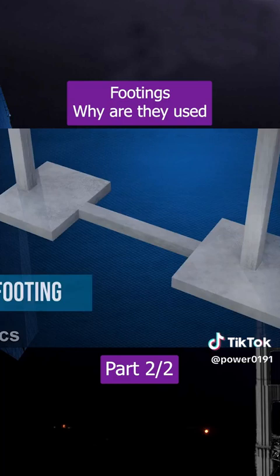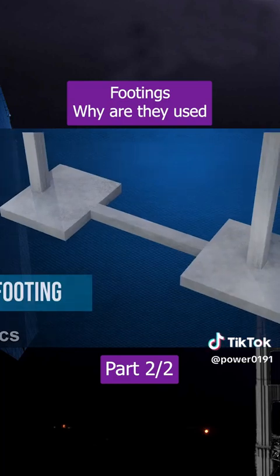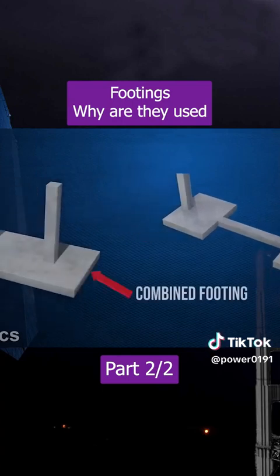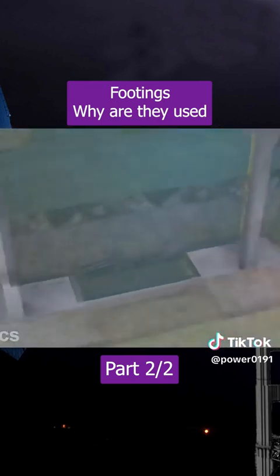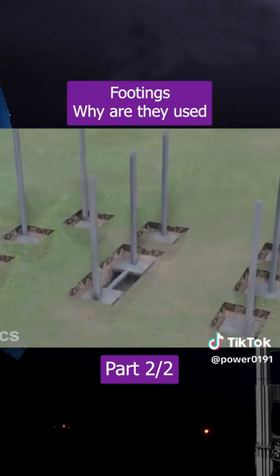One of the columns in this strap footing will generally have an eccentric footing. Moreover, in some cases, when the columns are too close to each other, engineers purposely combine the footing. In most modern heavy buildings, the structure's columns are provided with combined footing as a whole.